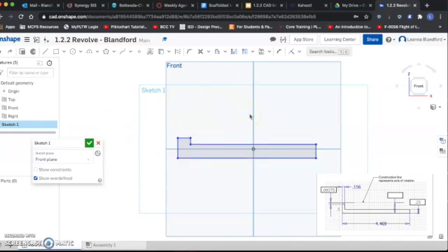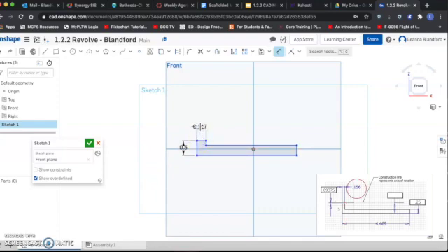And now that I have created that overall shape, I need to dimension it. So let's start. I like to go in a circle and start from left to right and just move clockwise across my drawing. So I'm going to start with this line right here, and the dimension on slide 6 for that is 0.5 inches. Then I have this distance right here, which is 0.156.